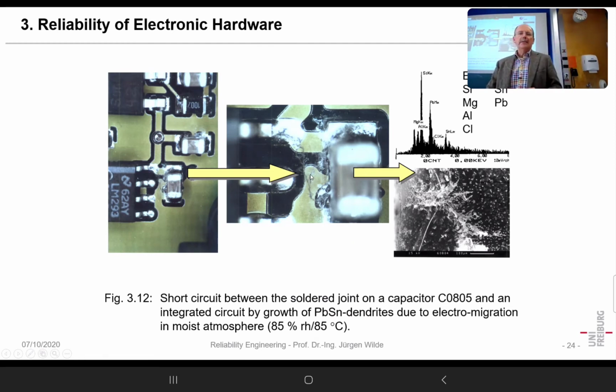And these trees were growing in this direction, and when they got close to contacts, they just evaporate. But of course, the processor doesn't like that, so you reset it probably, and in that way, you get a fault. It's not a failure really, because after that it will work again if you reset it. But in the end, you could say that was a very good example of corrosion-induced failures.